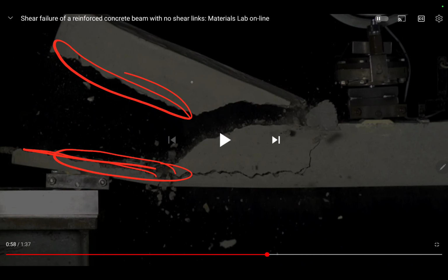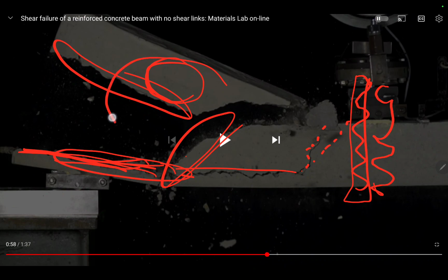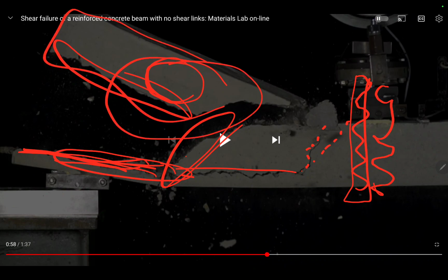It's trying to hold that bond I spoke of, I told you about, and the fracture happens there, where it breaks apart. We first see it with our eyes here. But at that point, this tension is so great in here, and you can see the load path here, in this case more clearly, that there's so much tension between the rebar and the concrete that we're seeing the break failure of this section. All right, let me back it up and do that again for you.